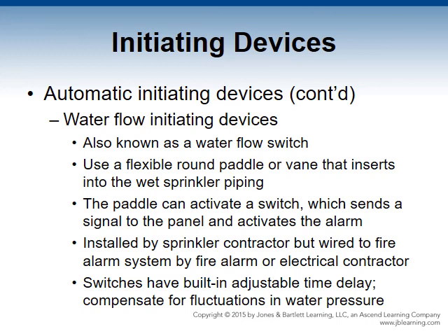The paddle size must also be correct to ensure that it activates correctly and does not block water flow or hold the switch in a constant alarm position. The switch has a built-in adjustable time delay to compensate for fluctuations in water pressure. It is usually pneumatic and can be set for no delay or delaying up to 90 seconds. Often, though, 30 to 60 seconds is typical when setting the alarm.